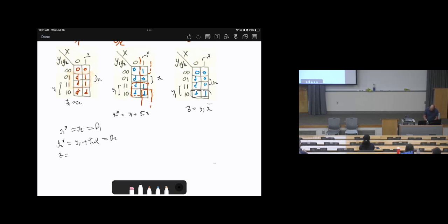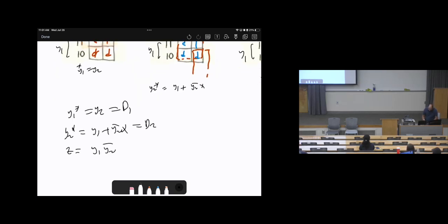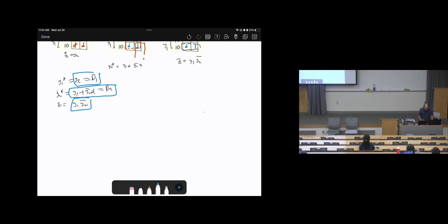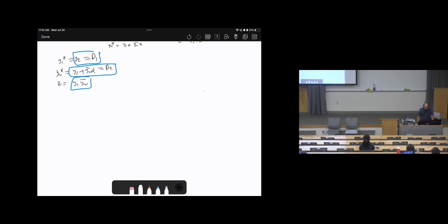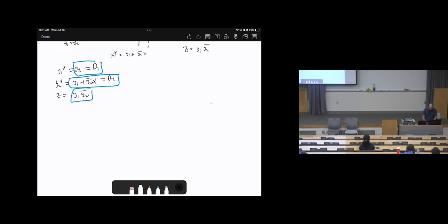And Z, remember, there is no flip-flop on it because it's time independent. Then now we know what's D1, we know what's D2. Then let me finish just drawing the digital logic circuit. I'm going to take a few minutes. In case you need to leave, you can leave. I don't want to affect you if you have other arrangements.